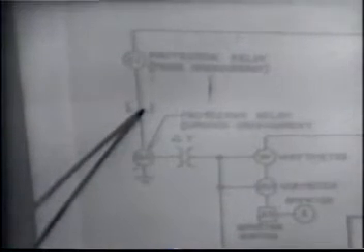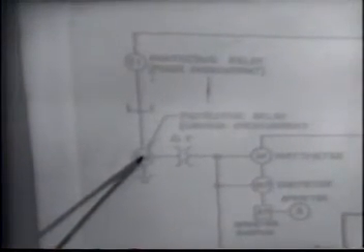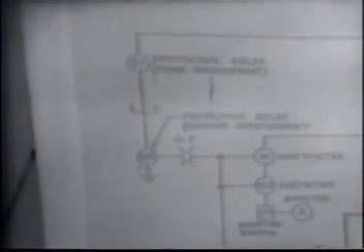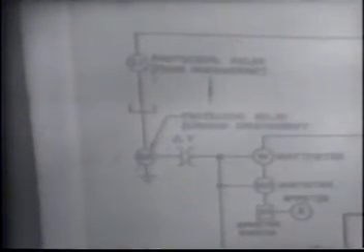Excuse me, I've got a question. Yes. Between your CO relay and your ground relay, what does that symbol stand for? That's a symbol which I did not look up in our standards, but it's a convention which indicates that at this point you have the three-phase currents have joined. This is in the neutral circuit going to ground. We use it quite commonly on some of our drawings. I think it's one of our Illinois standard symbols, but unfortunately I didn't check our handbook of symbols before I brought the sketch here. But that's the point at which your phase currents join for the neutral return path.